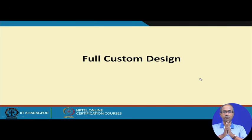Now, let us come to full custom design. Now, for the standard cell or the semi custom design, what we had assumed? We had assumed that the cells are already available to us, their layouts are available, their geometries are very well defined, their heights are same, the relative vertical positions of the VDD and ground lines are the same. So, I can simply put the cells side by side.